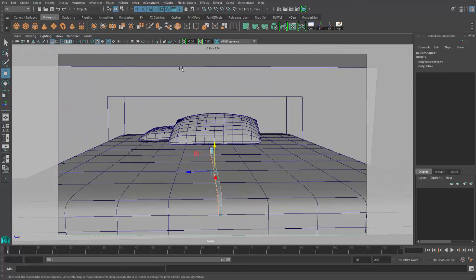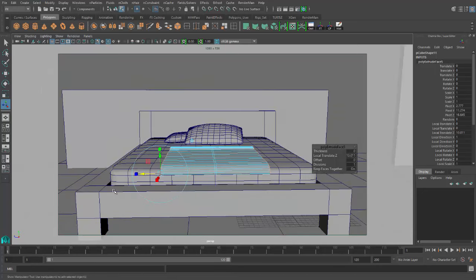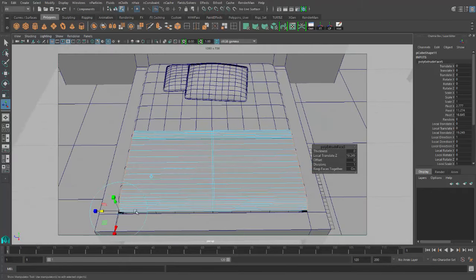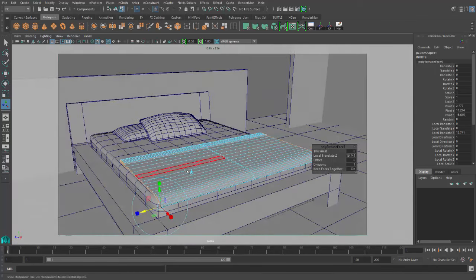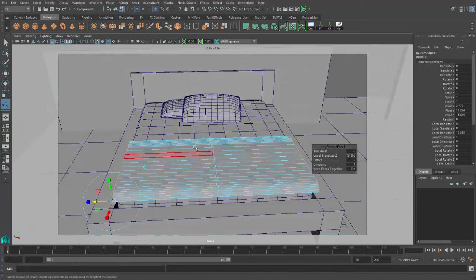And what we'll do, we just click extrude and let's just pull it out. Okay, don't know if this is in the center of the bed. Well, we can just have a look at it. Okay, right, so maybe I just pull a little bit more. And if you want to work with soft objects, something like the pillow, you need to have the subdivision. So for the extrude, I can increase the division. That's going to give us a little bit more control. Okay, maybe 14 is enough. If I'm happy with it, I'm just going to change to the move tool.